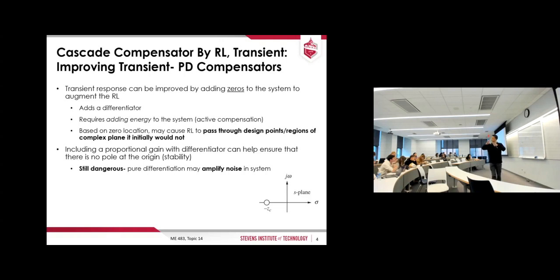After putting together this PI controller by putting the pole at the origin and then a zero near the origin, remember? Through the pole-zero cancellation, although this increased the type of the system, type 0 to type 1, it acts as if there was just the original second order system, thereby not changing the design point. It changed it a little bit. But it eliminated the steady state error. That was what we did last time. Yeah? You follow what I say, 90%? Give me 2 claps.